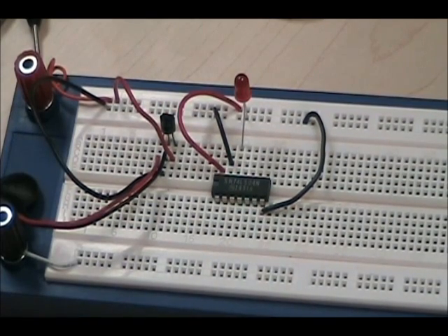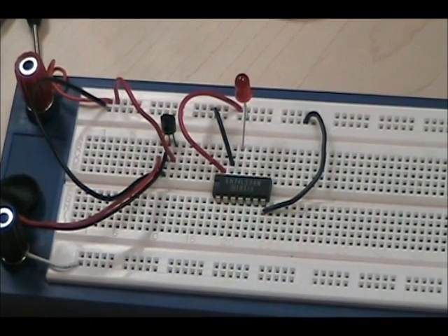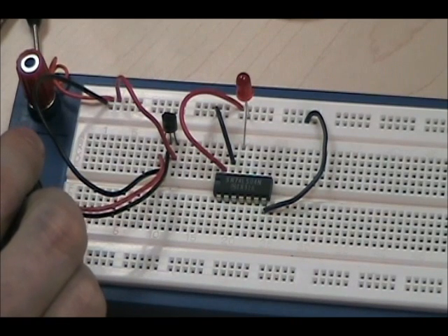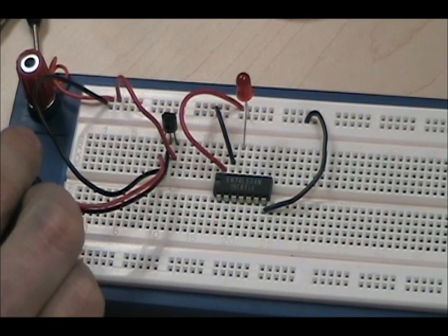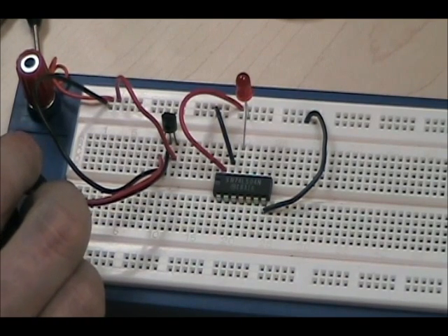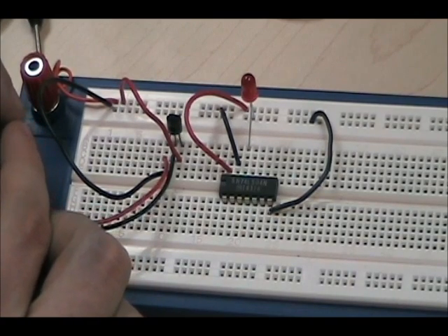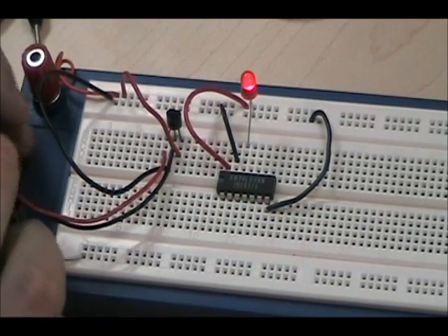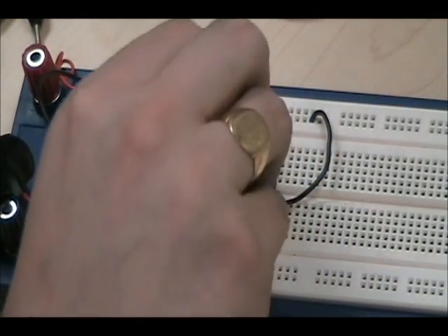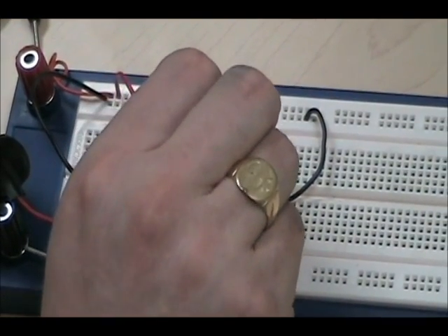All right guys, this is the 74LS04 NOT gate. We're going to power it on. We've got its one input. Remember, NOT gates only have one input and one output. The output is the opposite of what the input is. So right now we've got the input at ground, at negative. So we expect that as soon as we turn it on, there you go. So as soon as I unplug this, by default the input is going to assume 1, which is going to make the output go low.